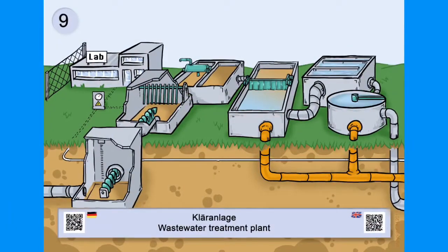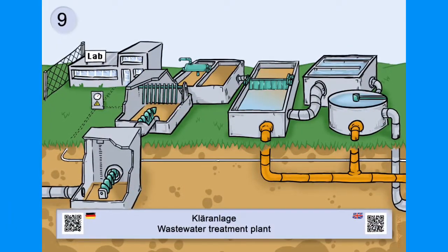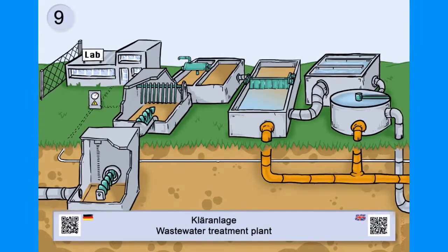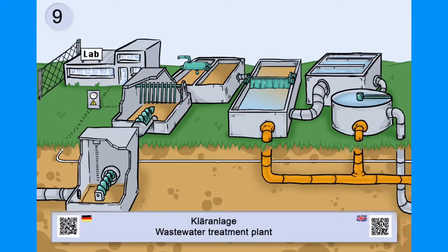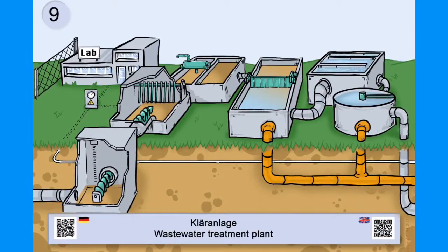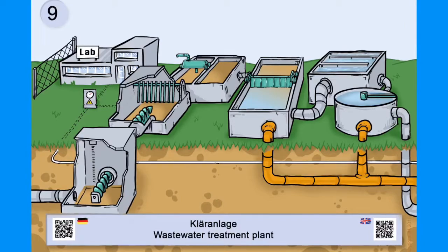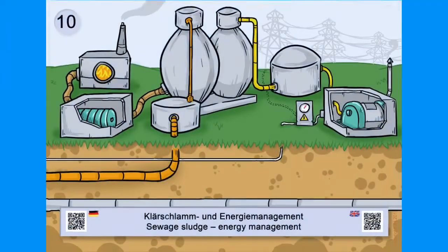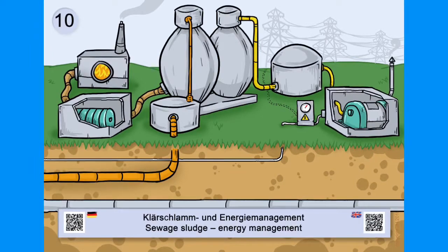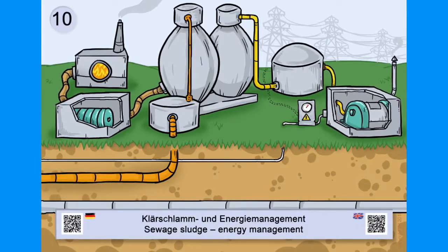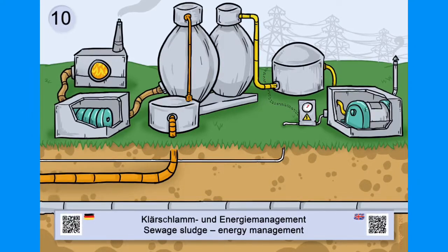The water goes into the wastewater treatment plant. First of all, you lift it up, then it goes to the screen, to the grit chamber, to the primary tank, activated sludge process, secondary clarifier, and then hopefully it's well treated and it goes to the further step. But it's not only what we treat, we also have to take care of the sludge, and the sludge makes a lot of headache all over the world.